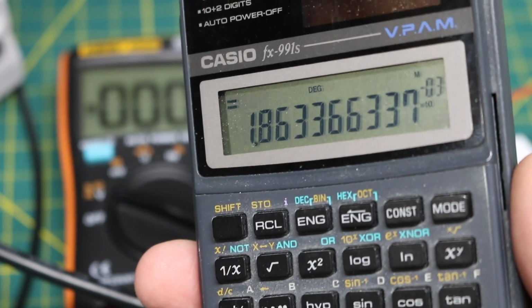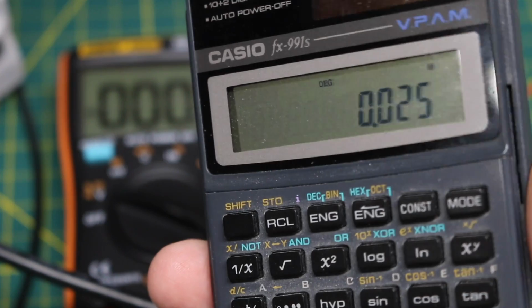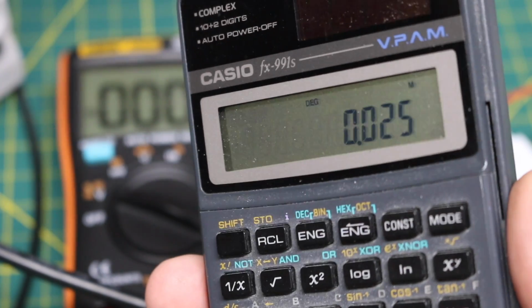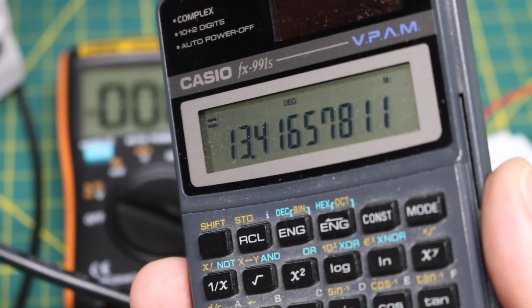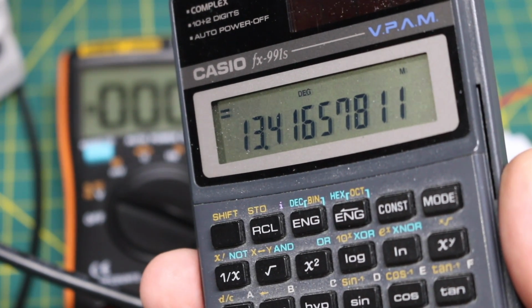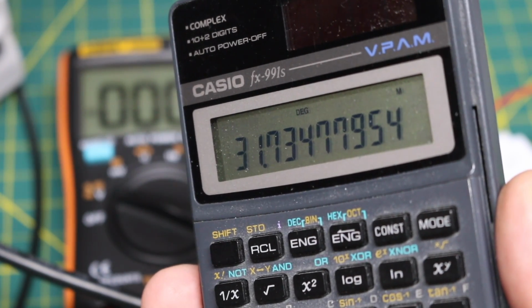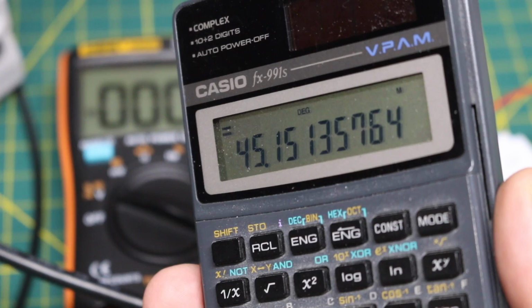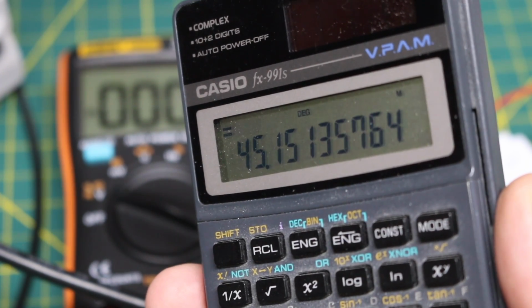So the impedance looking into the emitter of the transistor is about 25 millivolts divided by our collector current, 13.4 ohms. Adding that in series with our external impedance of 31.7 ohms, we have around 45 ohms of emitter resistance to factor in.